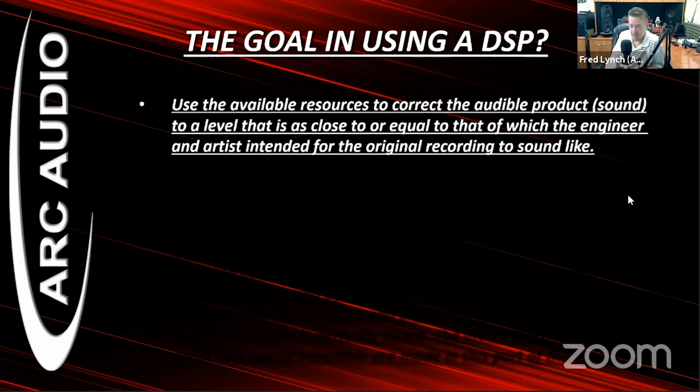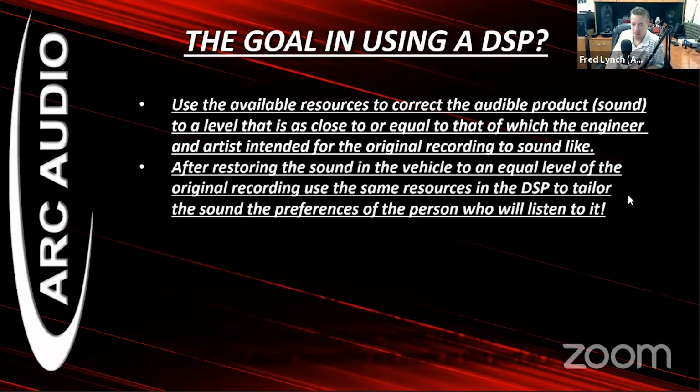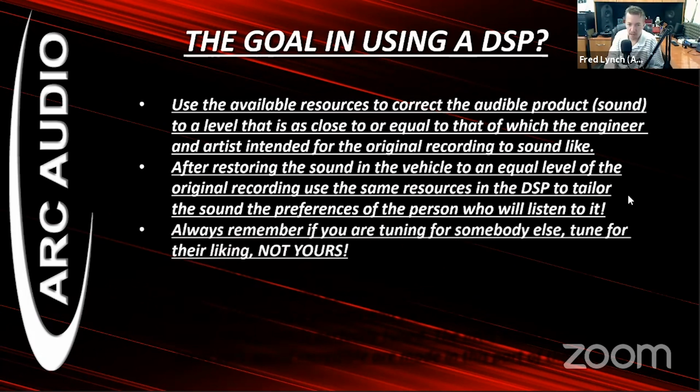That's great if you want it to sound like the engineer wants it. But the idea is you can use this reference, and this is a goal to correct the sound, to get yourself to a point where you can tune it and make the tweaks that you like for the way you listen to music. After restoring the sound in the vehicle to an equal level of the original recording, use the same resources in the DSP, equalizer, even delay for some people, to tune it for where that person is going to listen to it. And always, if you are not the person who has to listen to this and you're the person tuning it for somebody else, tune it to their liking, not yours.